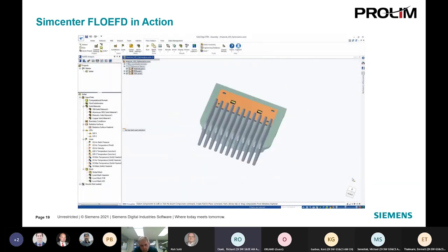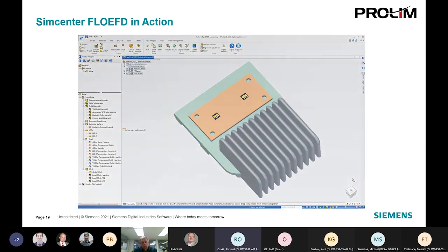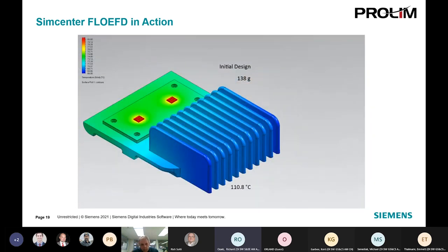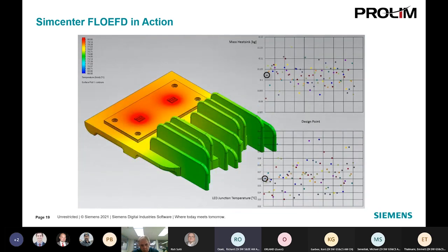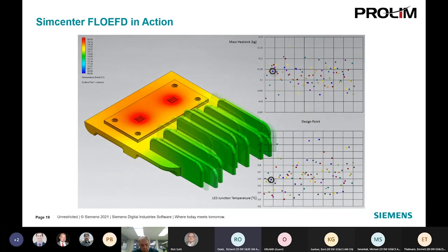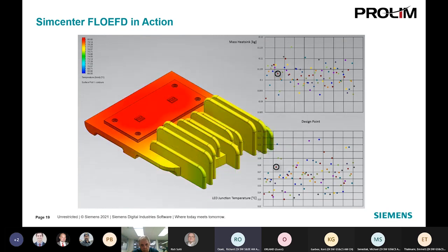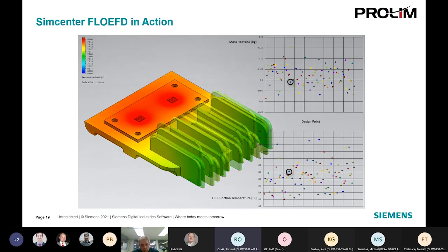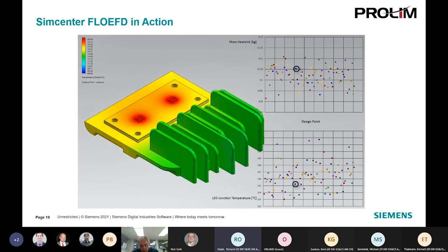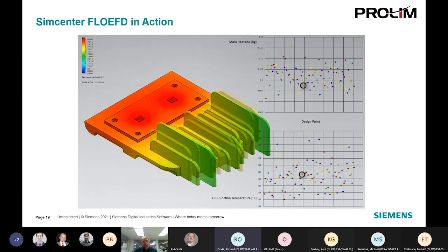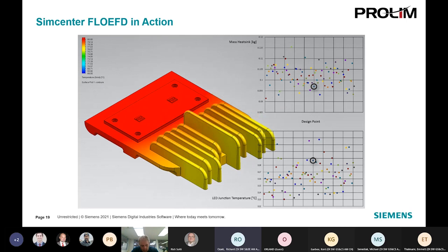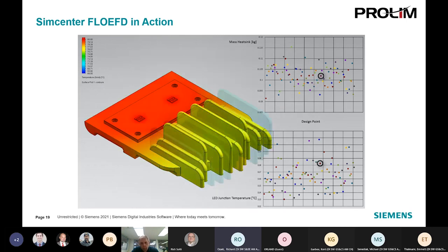All right, let's have a look at another example. This is an LED streetlight, and we've got a heatsink that's been designed here. And again, because we've got access to the parametric CAD features, we can drive variants such as pattern parameters, sketch dimensions. We can use our built-in optimization algorithms to really explore the design space and find the most optimum solution.